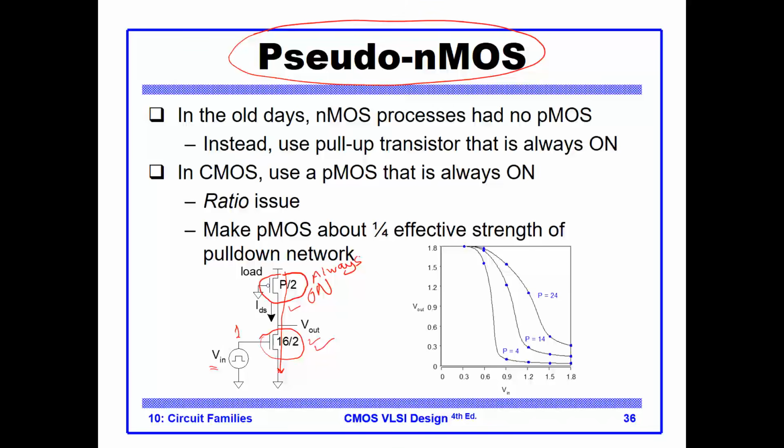And to simplify what happens, really, we can think of the PMOS device as a resistor and the NMOS as another resistor, and voltage divider rule will tell me the value of the V out. Now, clearly, what I want in this case is that the V out should be low as much as possible. So at the receiving end, whatever gate here receives the input, it will interpret this V out value as 0.